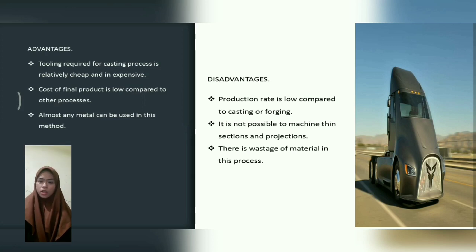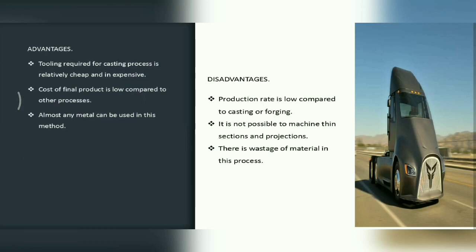So what are the disadvantages of this process? The first one is the production rate is low compared to casting or forging. The second one is it is not possible to machine thin sections and projections. The third one is there is wastage of material in this process.